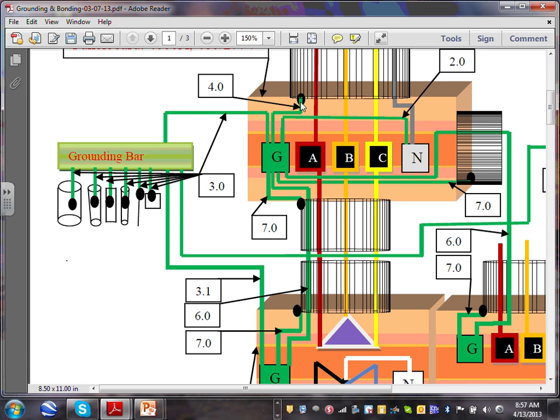Cool. Another example: you're coming into a 200 amp service with rigid threaded conduit with lock nuts on both sides, tight. That also qualifies as the supply side bonding jumper. How about a bonding bushing? If you put a bonding bushing with a wire and tie it to the ground bar inside your switchgear, that's the only time you need a wire supply side bonding jumper.